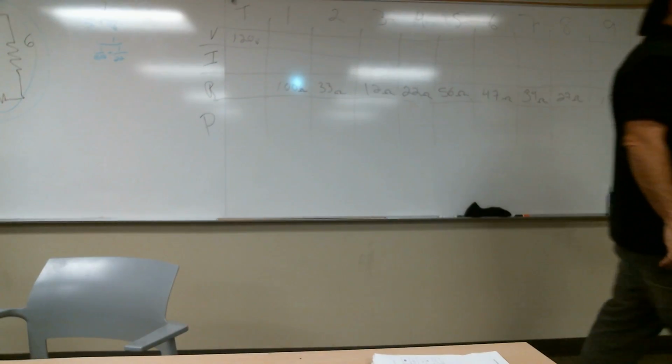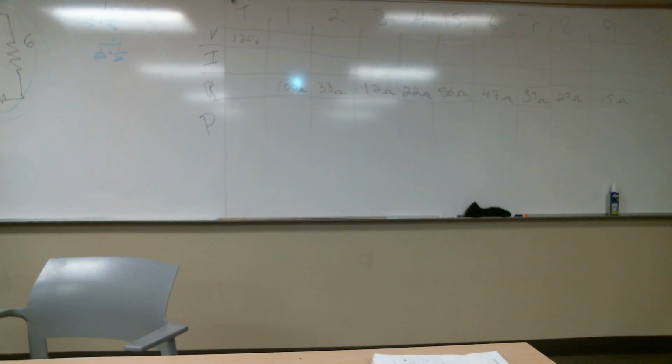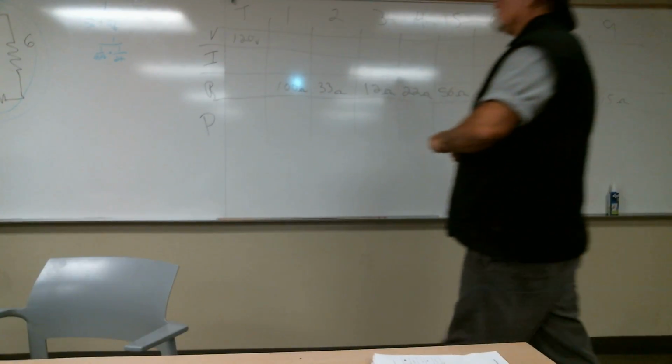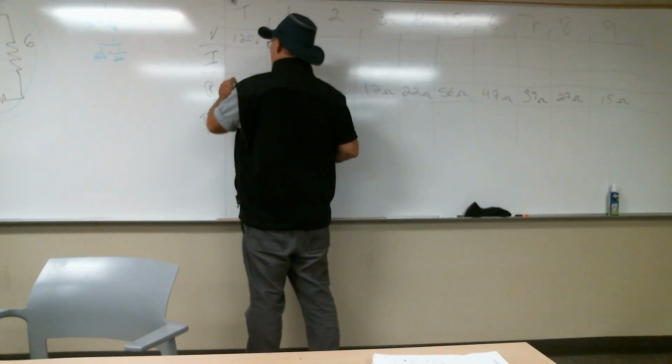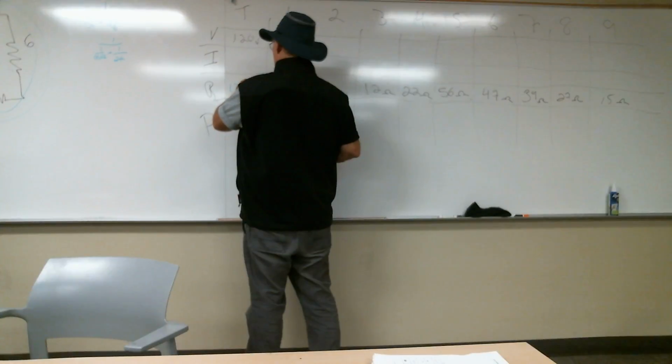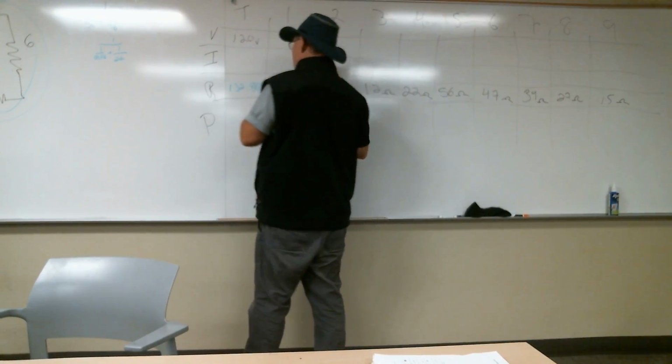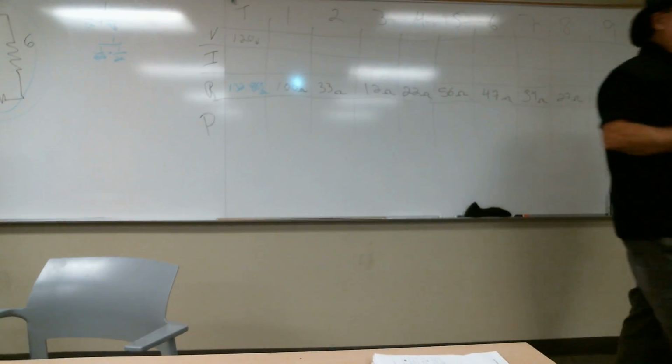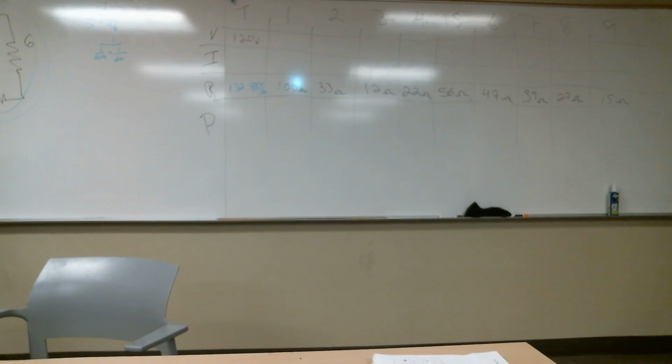All right, so now the only thing that's left is a series component, right? So if I take R1 as 100 and R9 as 15, that's 115, and 17.885 would be 132.885, and that's going to be R sub T. 132.885 ohms, and that solves for R sub T. Everybody okay with that? All right.